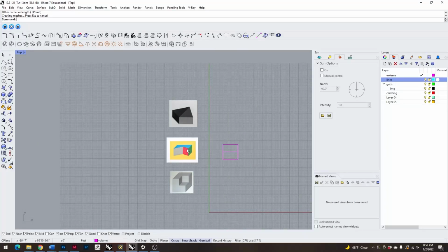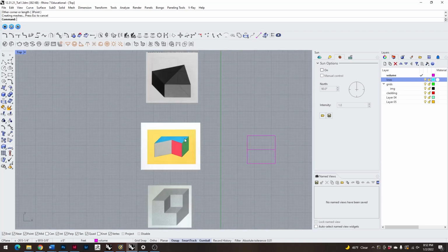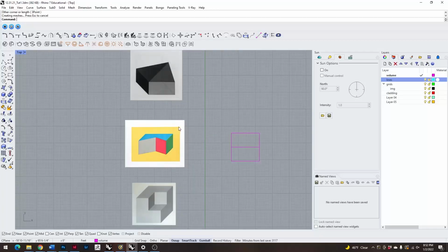The important part, because we're going to be working with grids, is we'll want to keep our geometry constrained to even whole numbers. So no 15 feet and 3 inches, we'll want 14 feet or 16 feet or 18 feet and so on. You'll also, the minimum width I believe is about 20 feet, and we don't want these to be any larger than 50 feet. So as you're modeling them, make sure that they fit within those general parameters.